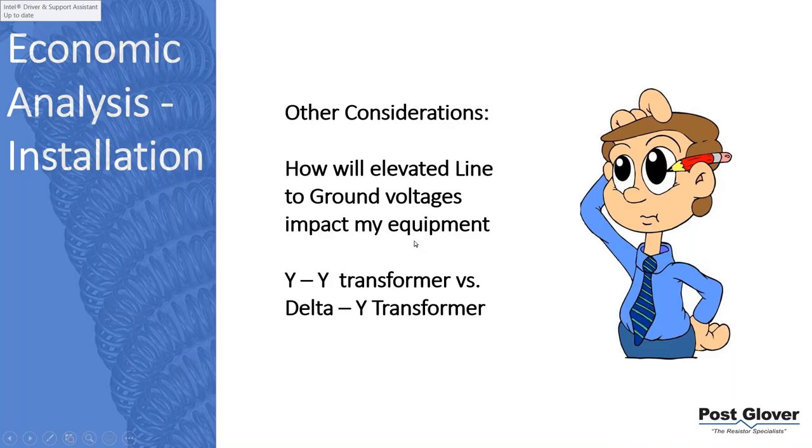But if you've used medium voltage high resistance ground before, let's just give a quick example. You have a 5 kV system. You want to continuously operate a high resistance ground system. You essentially need a 5 kV cable. So that bump up in cable throughout your system could be a significant cost increase. So I'm just trying to differentiate.